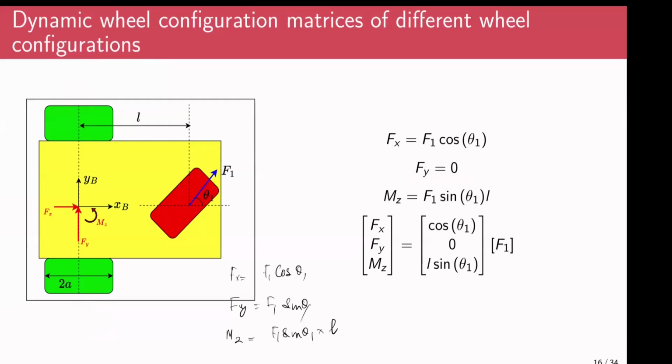Because if you imagine this wheel in a fully vertical direction, and you're trying to drive it, it won't move, right? Because the wheel will provide infinite resistance, and as a result, it cannot slide in this direction. And as a result, we consider the net force along Fy to be zero, because these are conventional wheels and they provide infinite resistance in the lateral direction.